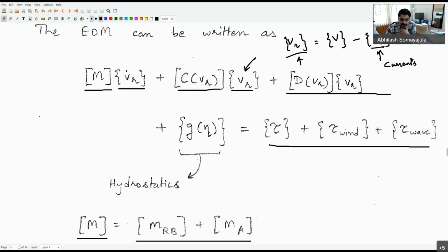And since I know that there is a representation of the Coriolis force which does not depend on the linear velocity, we saw that in a previous class, remember, where we tried to parameterize this in such a way that the linear velocity actually doesn't affect it. Yes, sir. Right? So therefore, I can pass the same velocity vector into the Coriolis matrix in its construction, and multiply that with this velocity vector, and I should still be fine. The only difference here is I'm accounting for the so-called ocean currents in this dynamics.